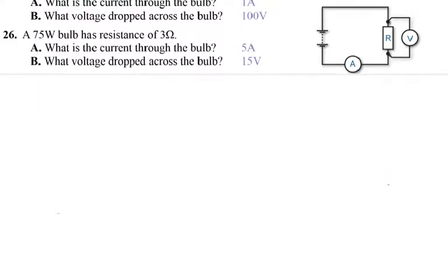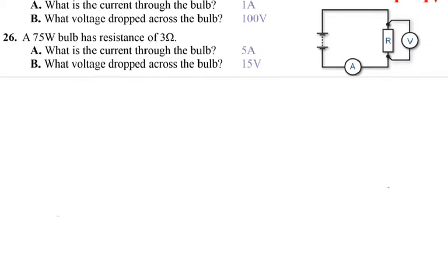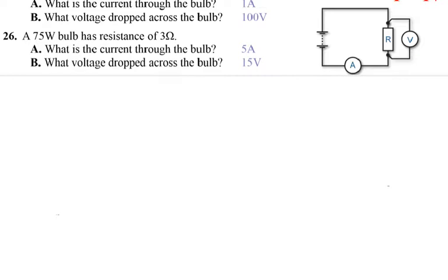Before I move to the next question, I also want to emphasize that it looks like I have here a battery. It looks like longer on the top and short on the bottom. Two batteries connected in series. If you needed to measure the current, you would have to disconnect your circuit and plug in an ammeter to measure the current.